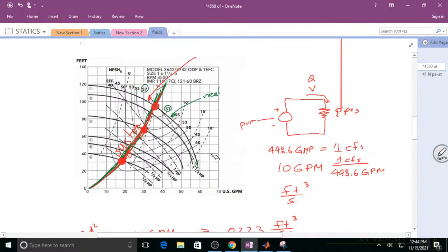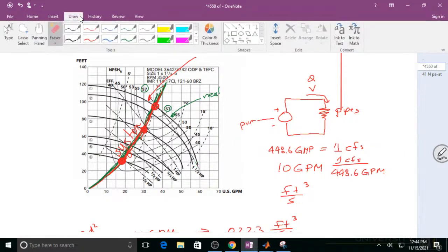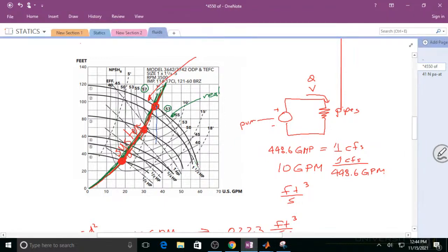let's say this is the thing. If you decide to buy this pump, you're going to operate at that gallons per minute and in that head. If instead you bought this other pump, essentially what's happening is each of these pump curves is basically either one pump operating differently with a different motor or a different diameter.